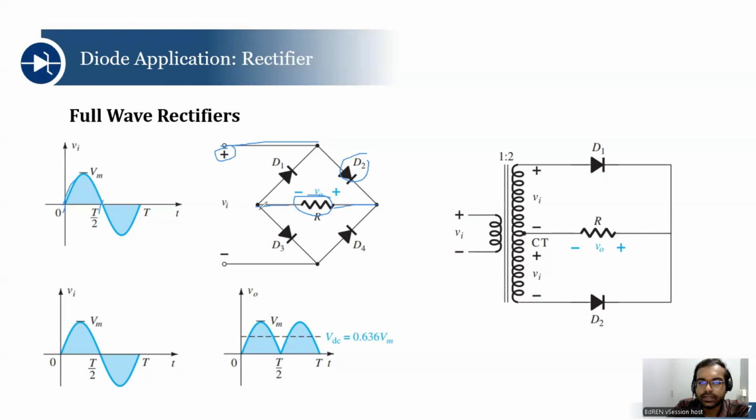And coming to there, this diode T3 will also be short-circuited. So current will flow from this circuit to here and will reach here. So the path is basically here through the T2, through the resistor R, and through T3, and it will reach here. So here in the output, we'll get this portion. We'll get this portion. Now for the negative half cycle, what will happen?